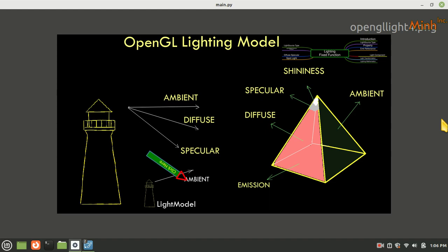So if we enable the light model and change its ambience, we can add or delete in the sense that the ambience of the light model can be changed. By default the ambience of a light model is, I think, 0.02. So the light model ambient, the ambient of the lighthouse, and the ambient of this material, all three come together to make the ambience of the material.